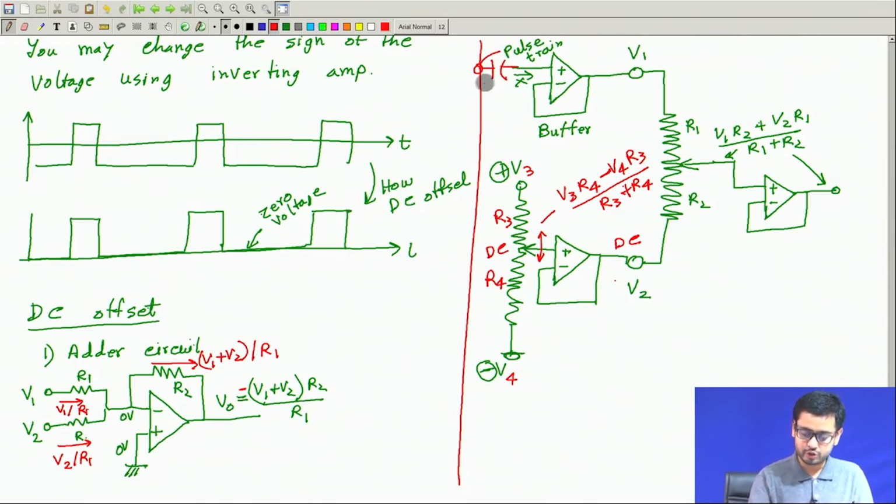So, if we want to remove the DC component that it has, that can be removed with this capacitor, and then with this arrangement we can add the desired amount of DC. So, any DC part that the original signal has will be gone, and the new DC part which I can control how much I want to add will be added. So, this is like a DC remover.